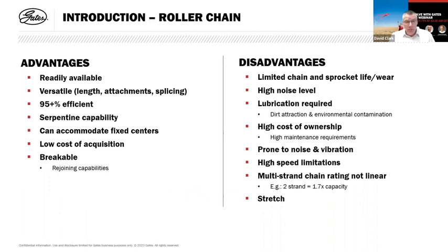There are speed limitations. Again, chains are relatively good at lower speed, but as you increase in speed, all of the disadvantages, I think, become more prevalent. Again, there are maybe some specialized chains out there which are more suited to higher speeds, but in the vast majority of drives, I think you'll find that a synchronous belt is more suited.